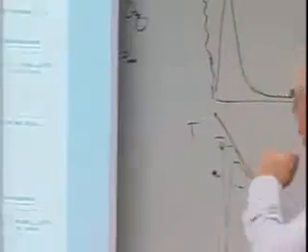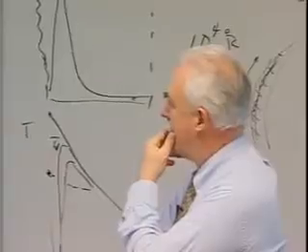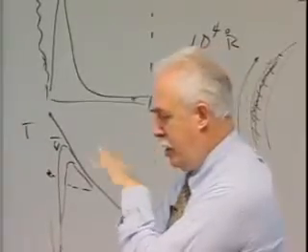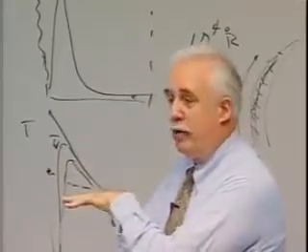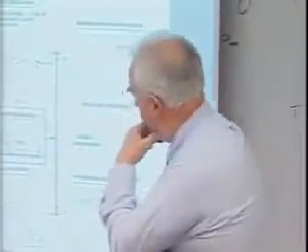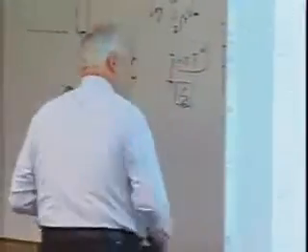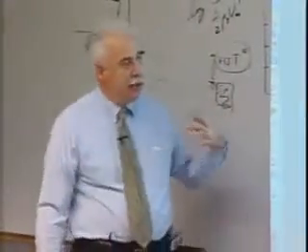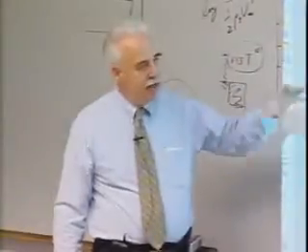Okay, boundary layer transition. I talked about the boundary between the turbulent and laminar heating. Characteristically, at the shuttle level, your heating goes up by about a factor of 3. If you go to higher Reynolds numbers, it can get significantly higher. So you want to avoid that factor of 3. Our initial estimate on the effective roughness, I have to say, was not as good as it should have been, but the technology wasn't really there. This is the logic, and I won't go through it in intimate detail, just to point out the complexity, to recognize the level of effort that goes into getting a basic database to design vehicles.